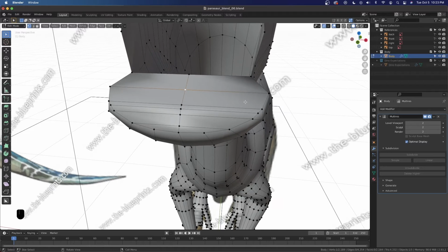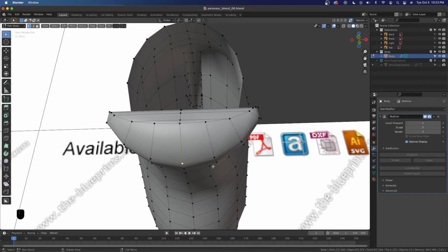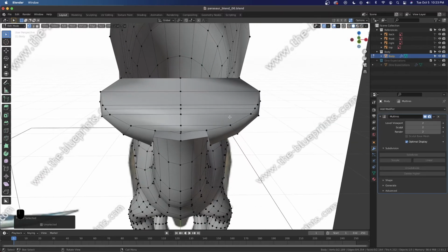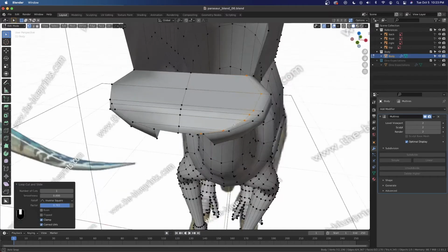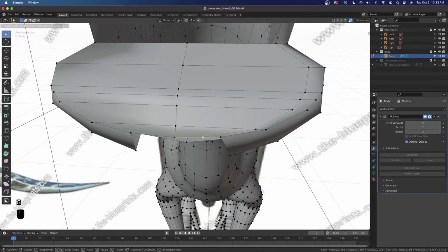We're looking good there. And now you want to add in an edge loop, but we don't want the edge loop to run through the whole body. So the thing you want to do is just go to the chin here and just hit H to hide. So now the edge can't run through because the faces are hidden here. So Control R. We're going to run this over here. This is going to be like the gum line. So let's go ahead and slide this over.